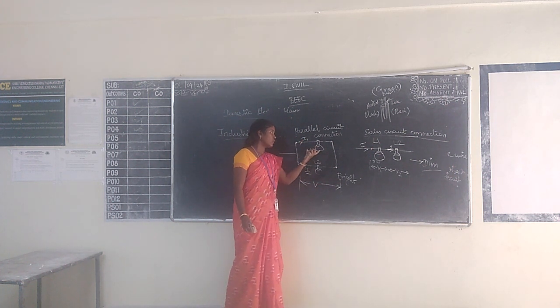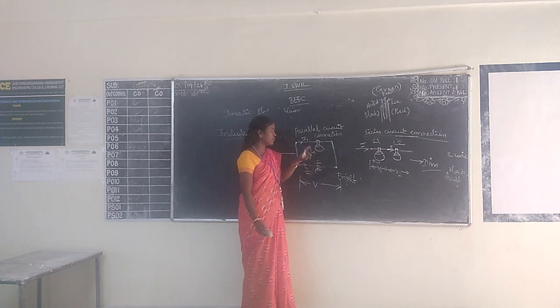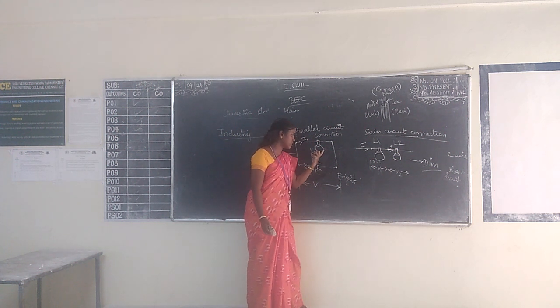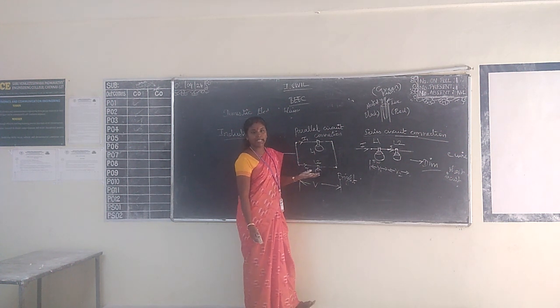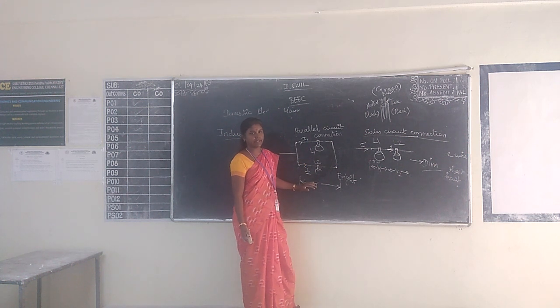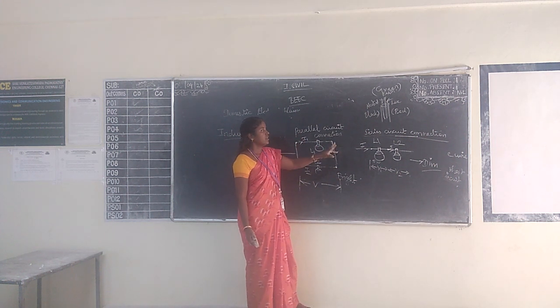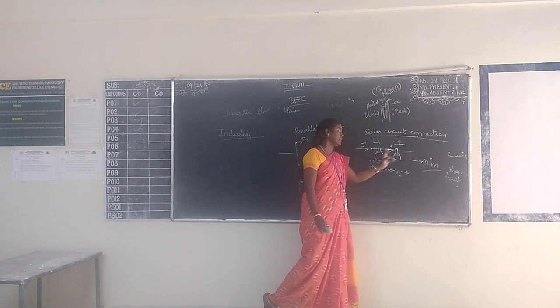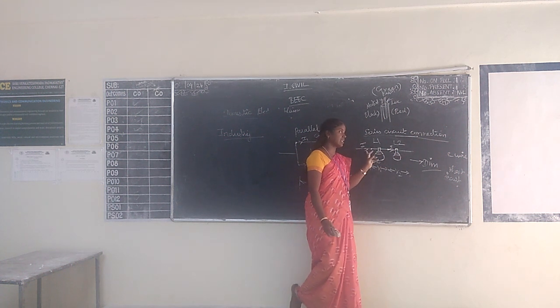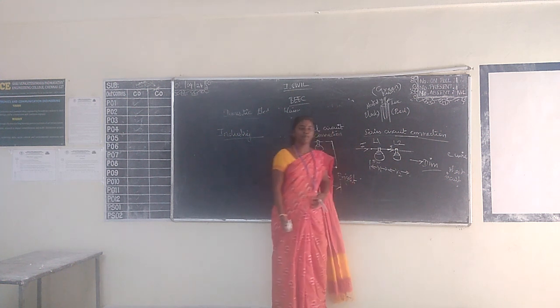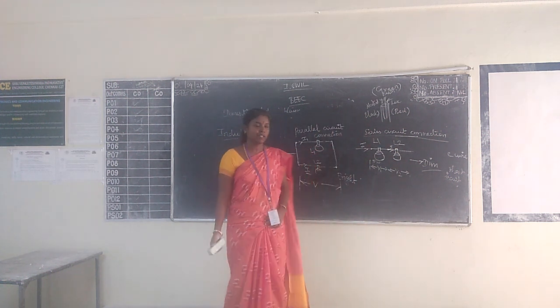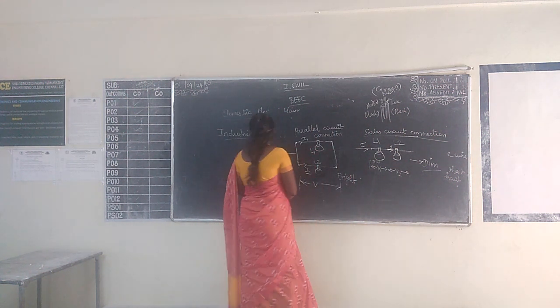So whatever amount of voltage we are applying for this, the same thing will be going to this also. Okay. So the same amount of brightness we are going to get in parallel connections. But the series will be a different connection. So here the current will be the same and the voltage will be different. So we are getting a dim lowness in the lamp. Okay.